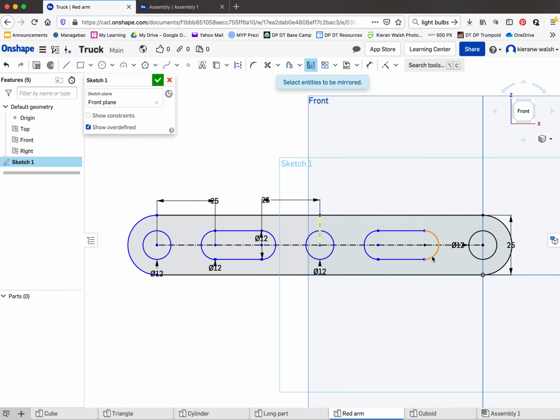Just to remember over here, this is all in one sketch. You shouldn't see any other sketches on your first sketch. You should be drawing everything in the same sketch. Some people run into a lot of problems, and if you see lots of sketches at the early stage of drawing an object like this, that's usually the problem. People somehow have made too many sketches. Just check over here. Yeah, it's just one sketch. Before you extrude anything, everything should be on one sketch.